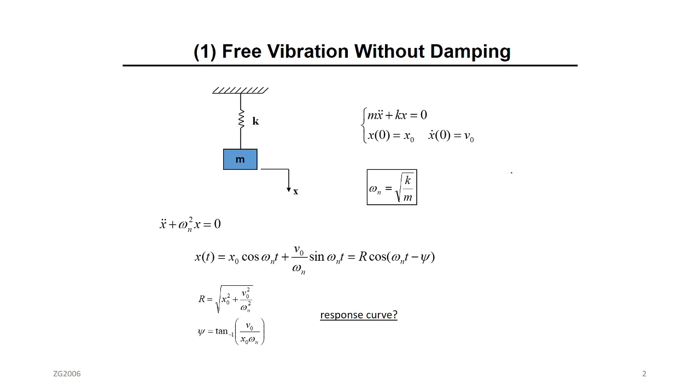We have a second order system, a mechanical system, without damper. So zeta here is equal to how much? Zeta will be equal to 0. Remember, zeta is the damping. How much damping do you have over the critical damping? So you have no damping, so zeta will be 0. Okay, this is the equation of motion of the system given. The model is given, with the initial conditions also given.